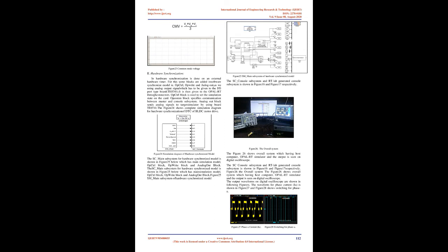2. Hardware synchronization. In hardware synchronization, synchronization is done on an external hardware timer. For this, some blocks are added in the software synchronized model, i.e. OpCtrl, OpWrite, and analog out, as we are using an analog output signal which has to be given to the I/O port type board, TE0741. It is then given to the Opal-RT through connectors. The OpCtrl block is used to set the simulation state on the card. The OPCOM block specifies communication between master and console subsystem. The analog out block sends analog signals to the target simulator using board TE0741.